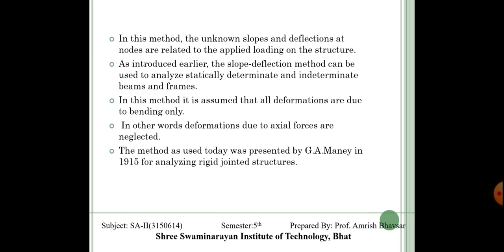In this method, it is assumed that all the deformations are due to bending only. In other words, deformations due to axial forces are neglected. The method as used today was presented by G.A. Maney in 1915 for analyzing rigid joint structures. Here we are considering that all the joints of the frame are rigid.